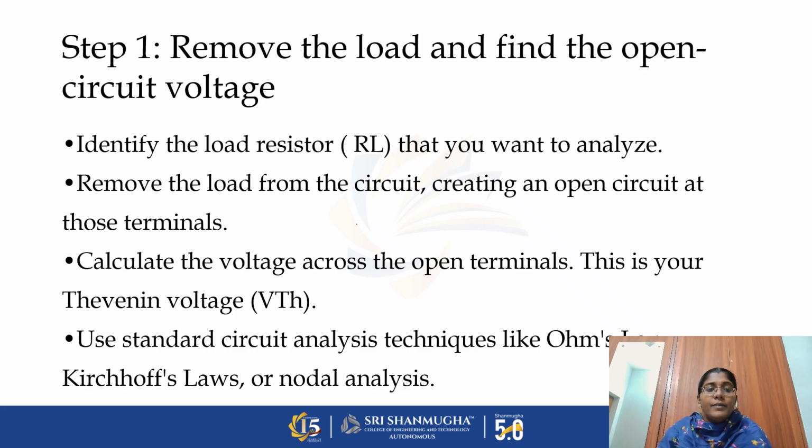And next, we have to remove the load from the circuit, creating an open circuit at those terminals. And we need to find the voltage across the open circuit terminals. That voltage is our Thevenin's voltage. Using standard circuit analysis techniques like Ohm's law, Kirchhoff's law or nodal analysis, we can find the voltage across the open circuit.